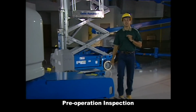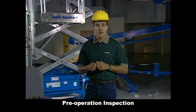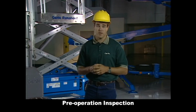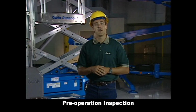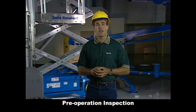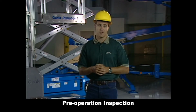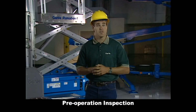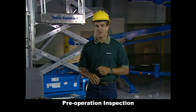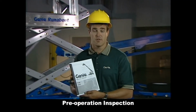A second key concept for safe machine operation is the pre-operation inspection and function tests. And why is this so important? Well, it's important because very often you don't know where that machine has been or how it's been maintained. This visual inspection is designed to keep the operator out of harm's way by discovering if anything is apparently wrong with the machine before the operator performs the function tests. You're looking for things like modifications, damage, loose or missing parts, and hydraulic or other fluid leaks. Your operator's manual has a complete checklist of items you need to inspect.